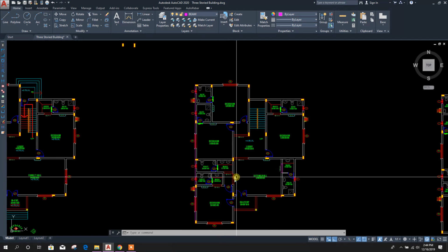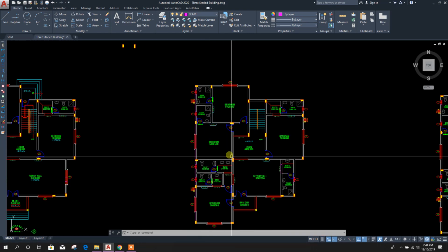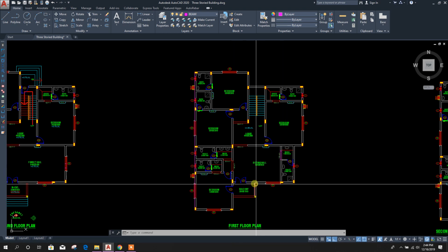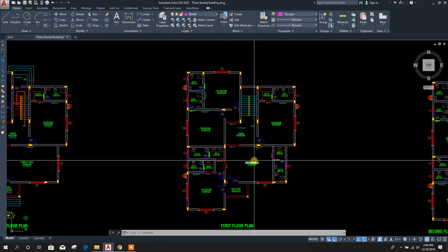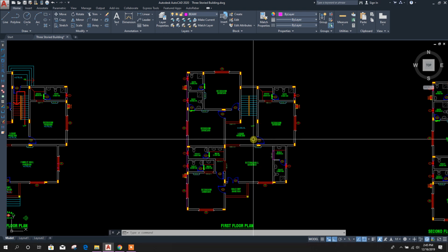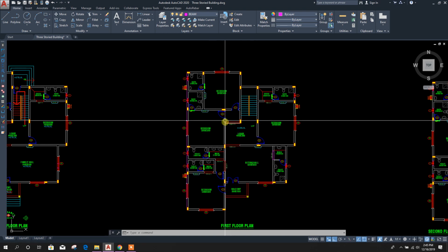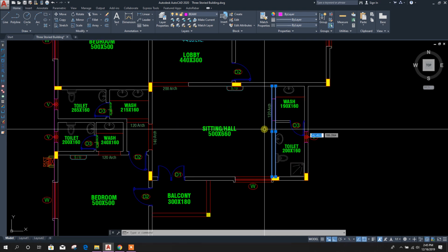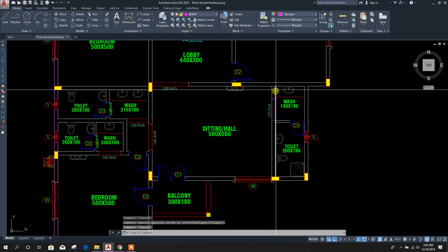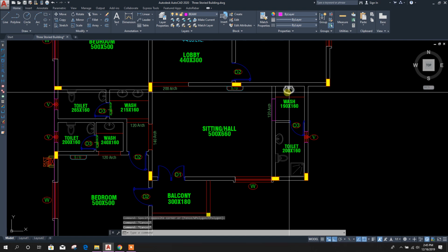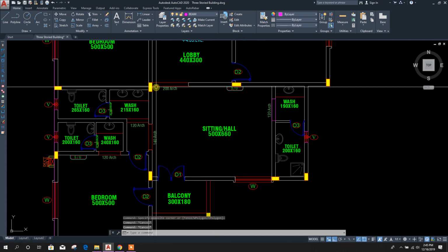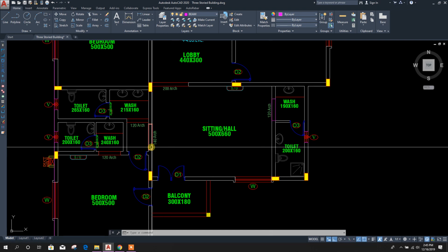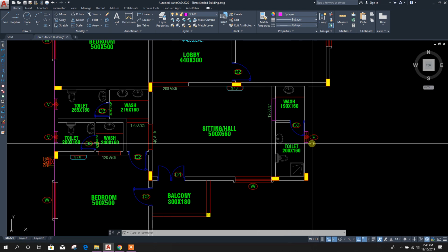So here remember two approaches. One approach is we provide beam under all the walls, and another approach is we provide beams only connecting the columns. For example, here if we don't provide beam, then we have to design this full slab area considering this wall load and this much bigger span.